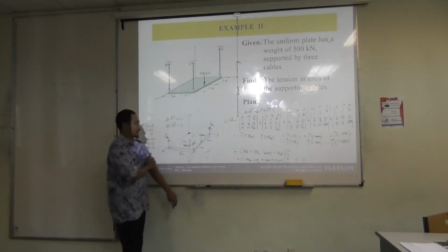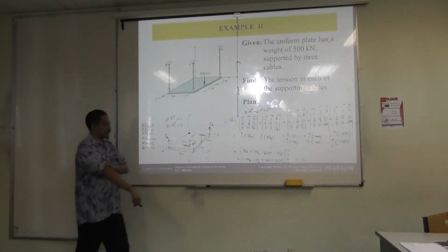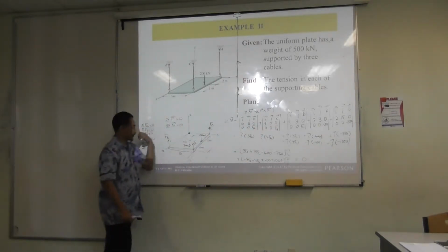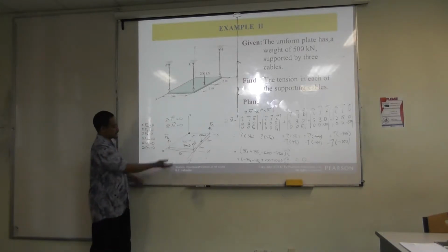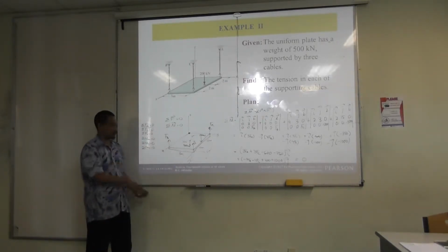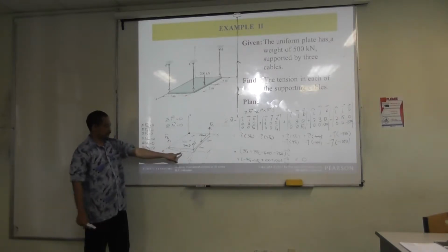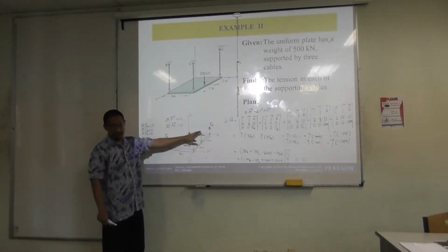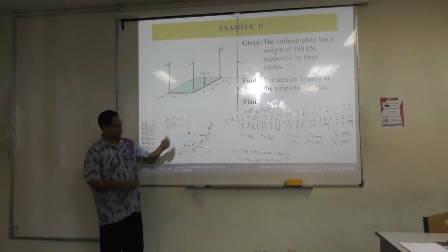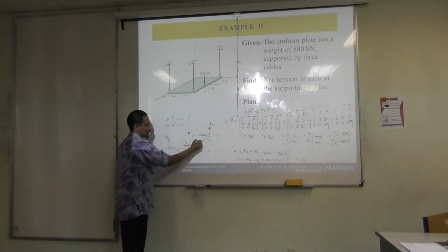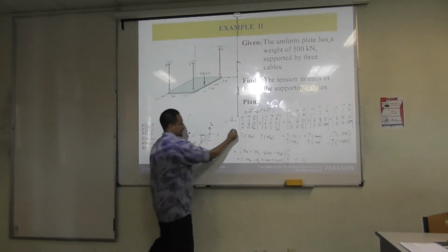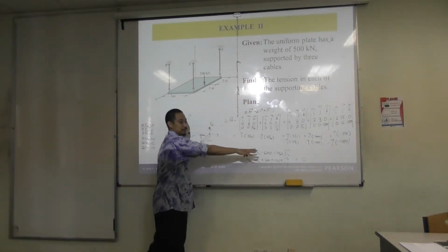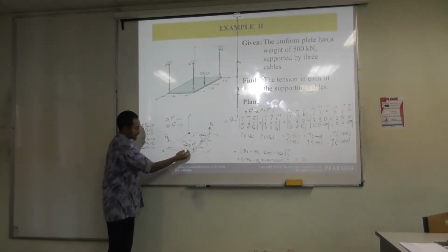The difference is, in this case, all the positive and negative comes straight away from this one. When we do manually, you have to assign positive and negative by imagining the clockwise, counterclockwise, right? Again, for this particular question, this seems much more difficult than just using scalar, right? But again, I'm just showing this because in case you have any angle like that, here is easier because you just change this thing, and then automatically the value goes there. But if you use scalar, then you have to resolve and you have to imagine everything.